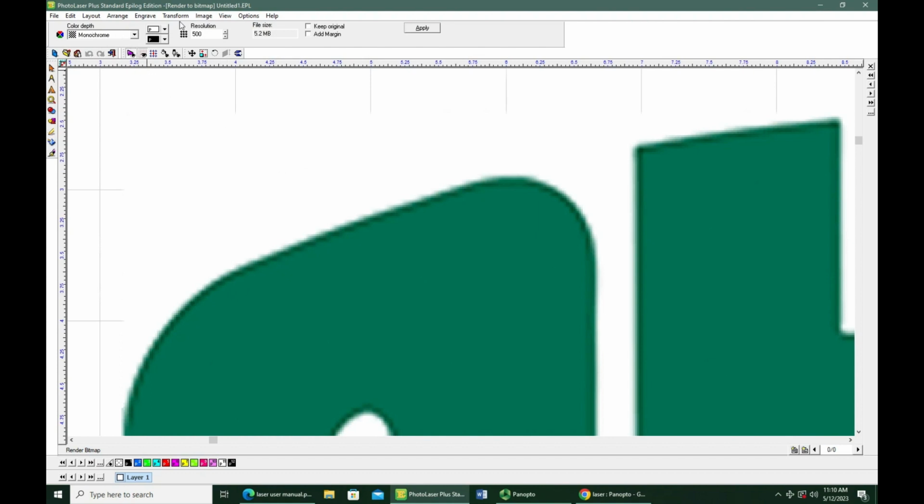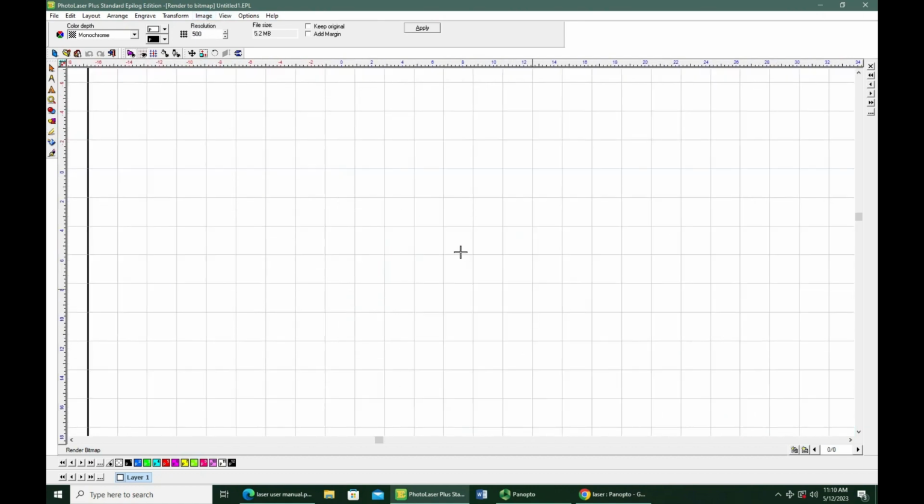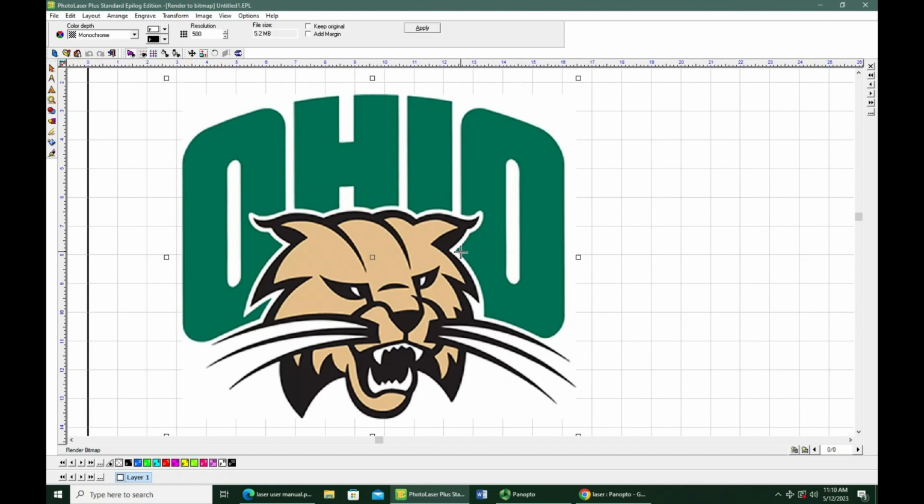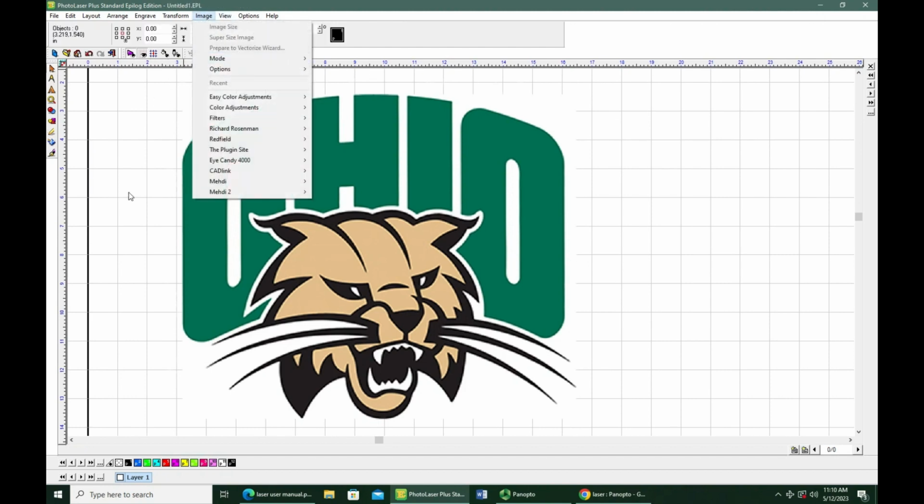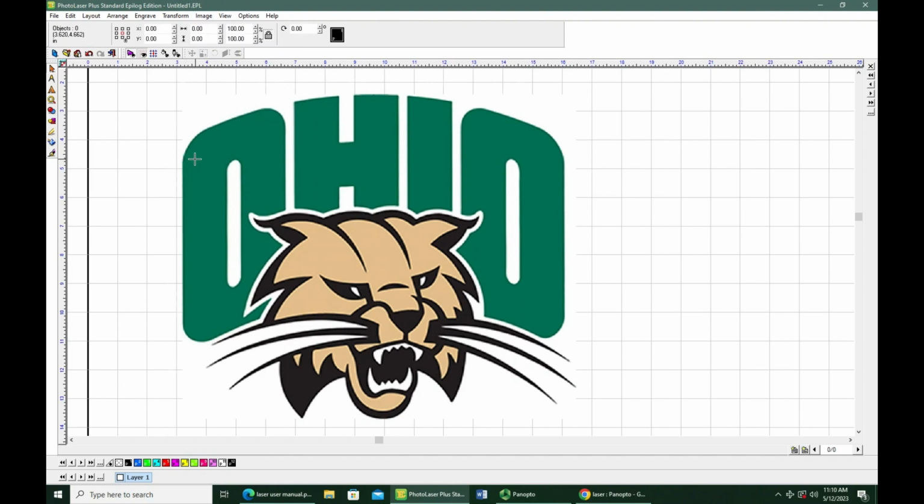Sometimes if you use this tool and then you use the vectorize, prepare to vectorize tool, that can also have negative effects. So you have to play around a few ways. There are 5 or 6 different ways to convert these over. Again, the quickest is just to do the monochromatic if that works. If that doesn't work, the next thing I would try is image, prepare to vectorize. If that doesn't work, I would go to SolidWorks and either A, trace it by hand, which is much quicker than it sounds, or B, use the SolidWorks auto tracing tool. I've never used it. I've heard it works pretty well.